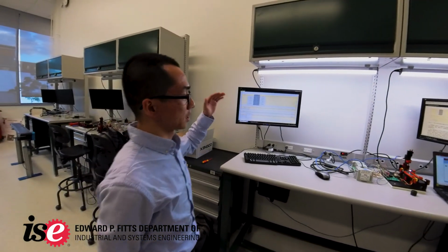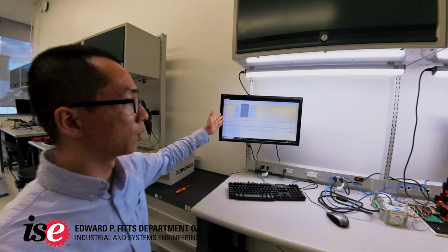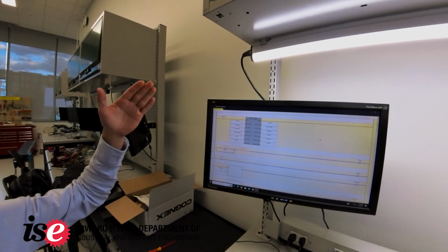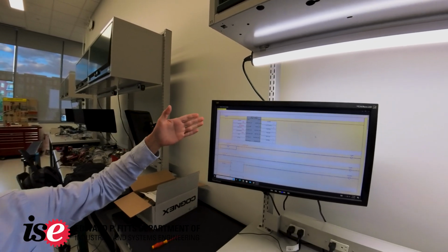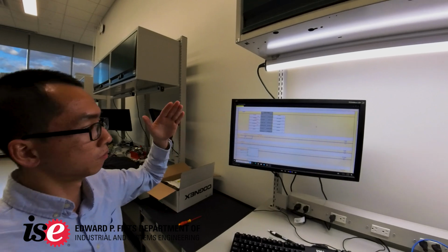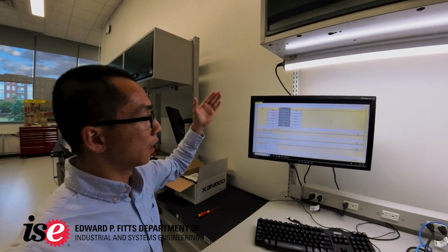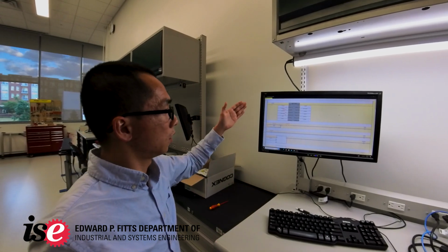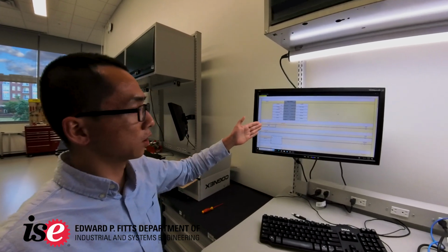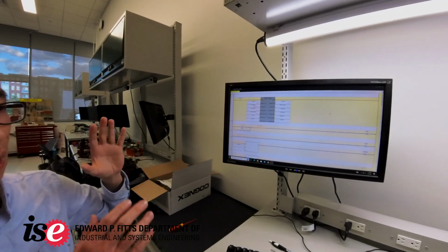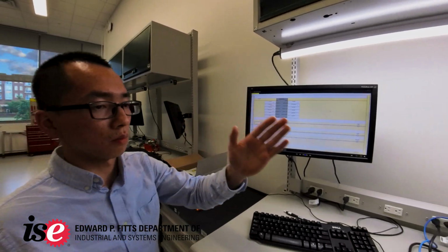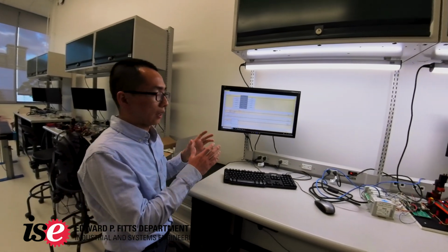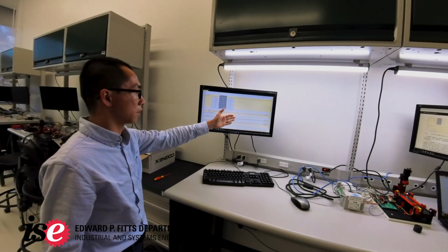Okay, so basically this is our code in CCW. The first line is about connecting to the broker, the MQTT Mosquitto public broker. And the second part is to enable the conveyor belt. So when the first sensor detects the object, it will enable the conveyor belt, and when the second sensor detects the object again, it will disable the conveyor belt.